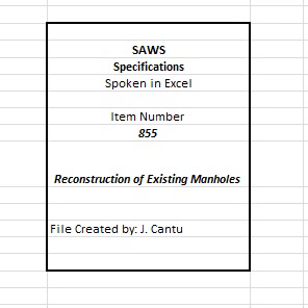5. If a sanitary manhole fails to pass one of the above tests, it shall be repaired in accordance with the manufacturer's recommendations and retested. 6. It shall not be accepted until it passes all tests. 7. All repairs and retesting shall be at no additional cost to SAWS. 8. Engineer of record must witness all tests over the EARZ.